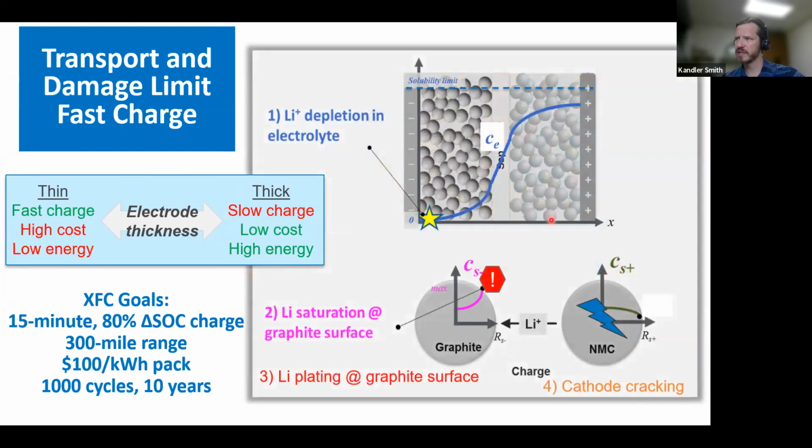And so the biggest limiters here are carrying the lithium ions from the positive electrode to the negative electrode. And diffusion is one of the processes that carries those lithium ions. When you deplete the ions at the back of this negative electrode, that means that if the overall battery is charging at a 6C rate, here you're at 0C.